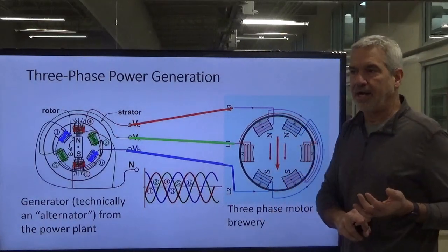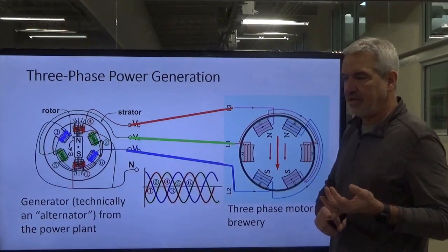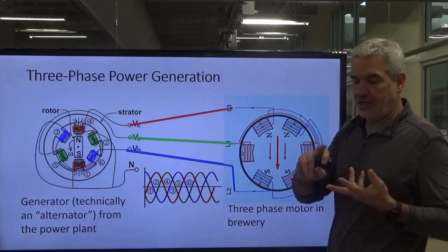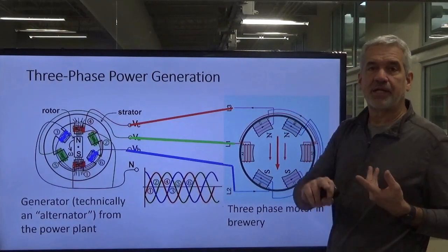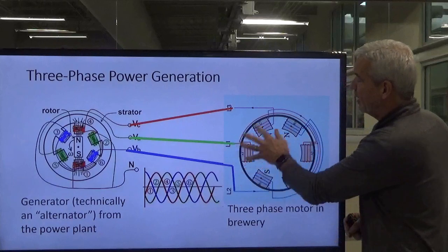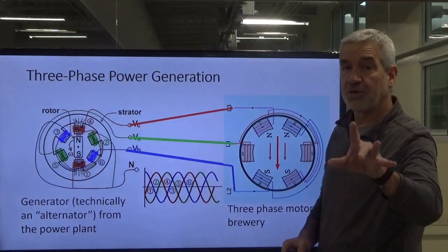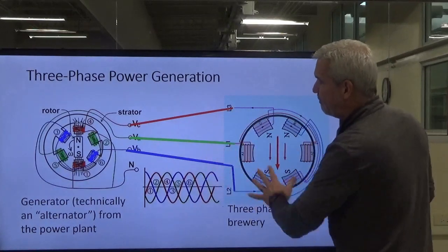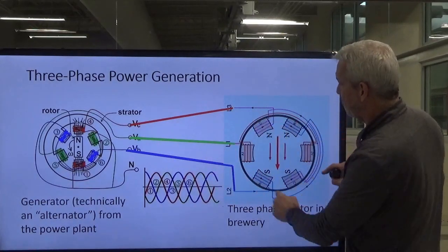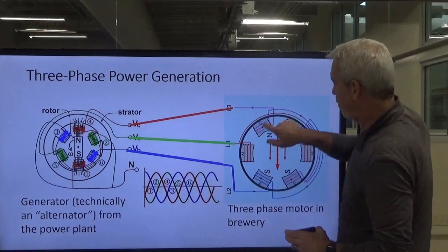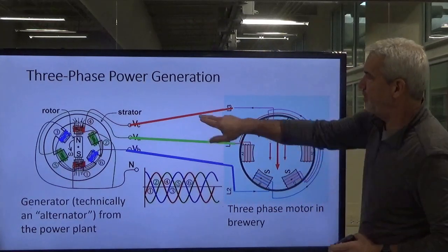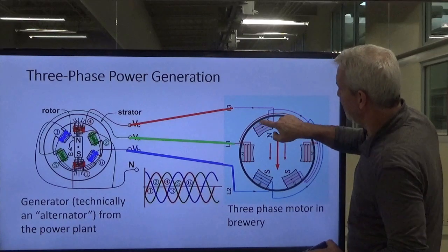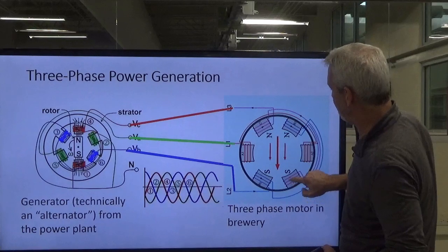And again, it could be a boiler motor, it could be the boiler elements for the heater, it could be a mill, it could be a pump, anything. But this is a 3-phase motor, okay? Some of them are single phase, and we're going to get into single phase later. But what we do is we hook these 3 phases of voltage to our coils of wire that are in a circular pattern here. And this voltage right here will come through here, and it will magnetize this iron piece right here and this one here as well.